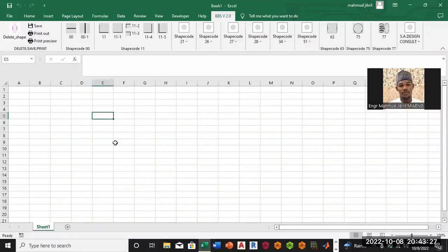In extensive terms, the bar bending schedule is a document showing the list of structural members, bar mark, type of reinforcement, size of rebar, number of rebars for each member, cut length, total length, shape, location, spacing, position of all reinforcement in the working drawings.